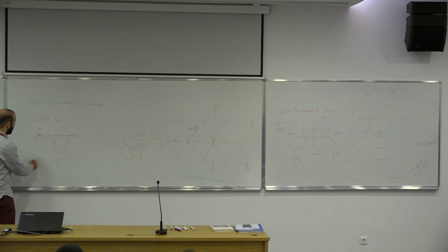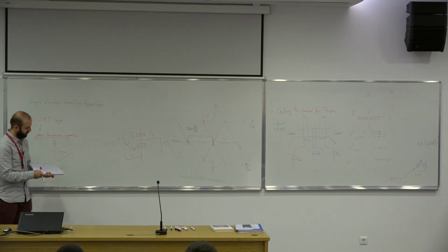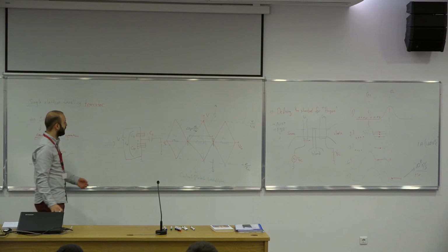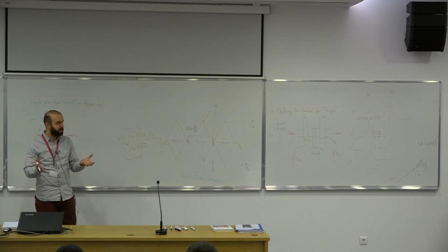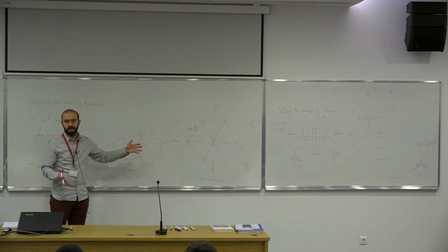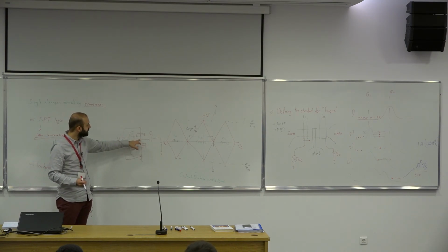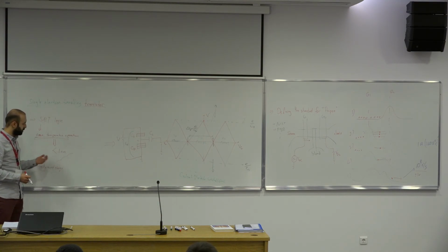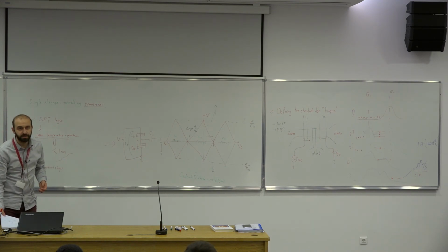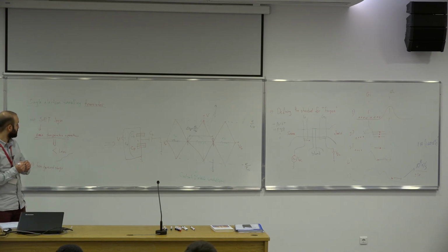And also there's another problem, which is typically this background charge. In a way, you cannot completely isolate this island from the environment. There are still charges floating around in this system, and that background charge modifies the energy levels within the quantum dot, which again leads to irregularities and unpredictable operation in single electron transistors.